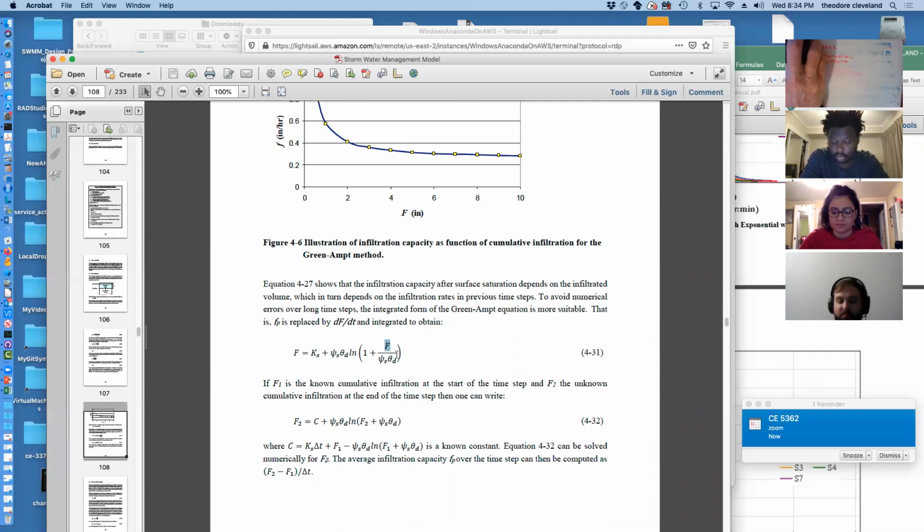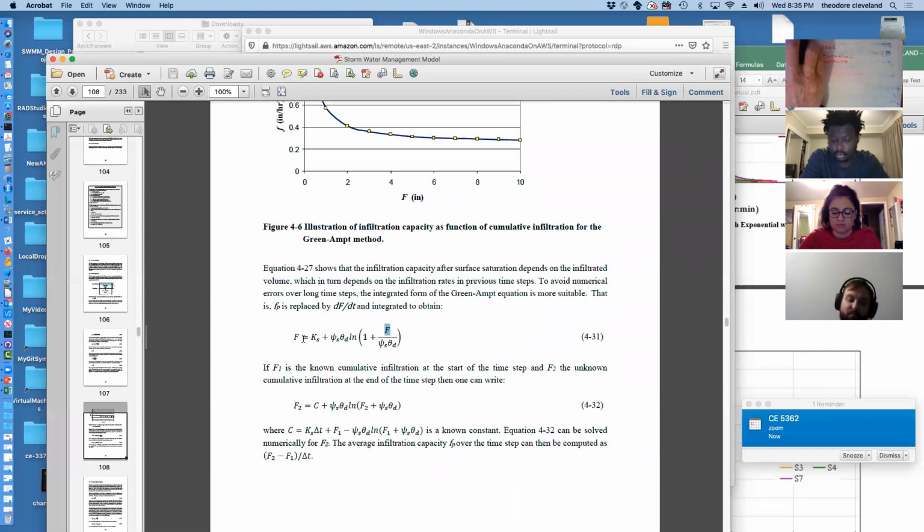The cap F is actually determined as the solution proceeds. You'll notice that cap F appears in two places. That's called an implicit equation, and that can't be simplified any further than that. There's no point. Because of that logarithmic term, you can't isolate the F and put all the other garbage on one side, which is not a big deal.